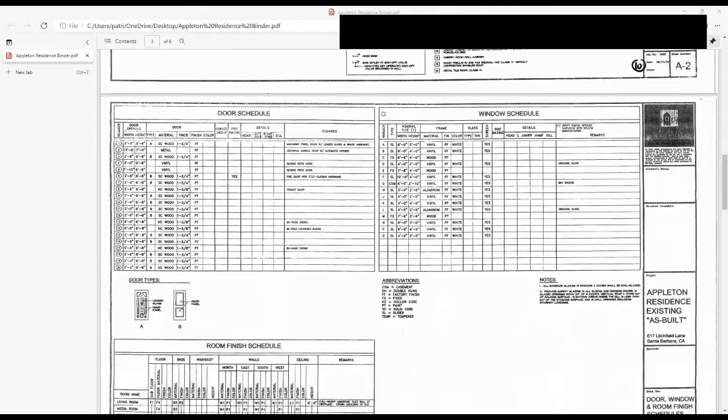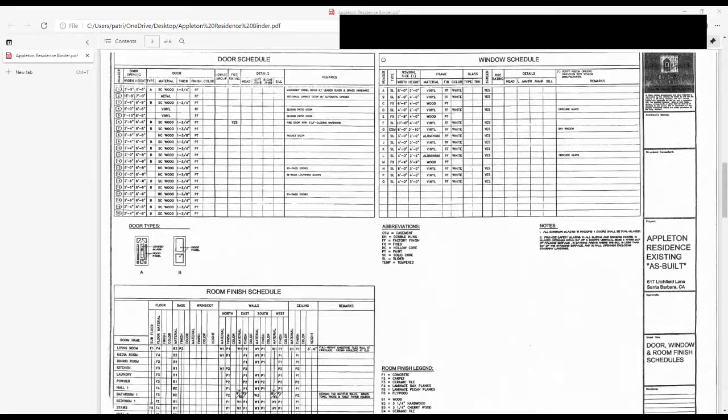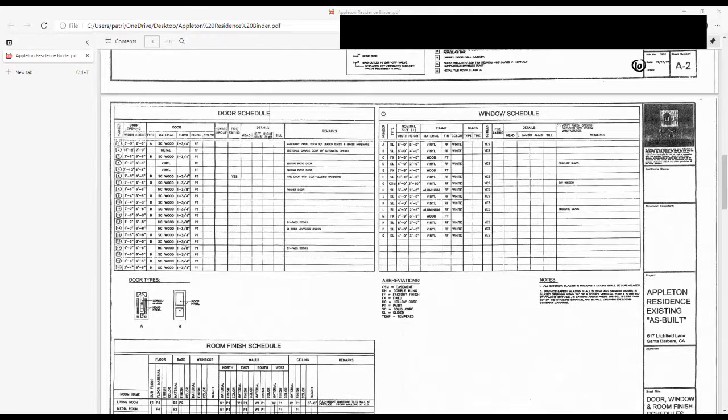And it doesn't use rough openings, which most prints do now, because the window company puts out the rough opening, and you need that before you frame. So if the architect designs a certain size window from a certain company that makes this particular type of door or window, they have to get you the rough opening before you frame. Otherwise, how would you know?